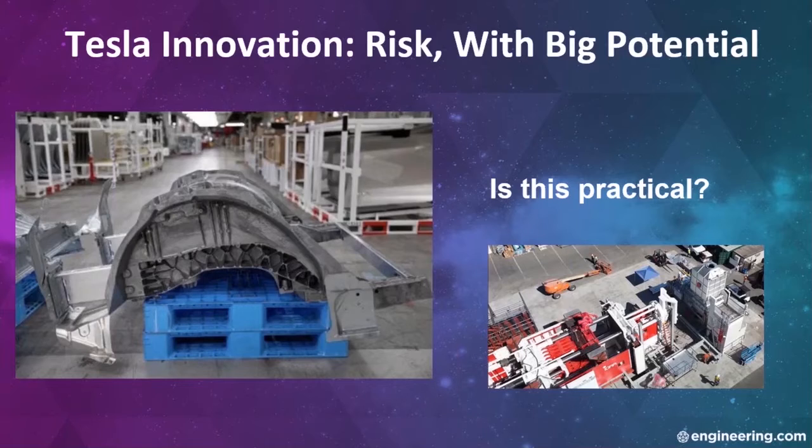Now, to attain the desired million unit per year production rate, multiple machines are going to be used, and Musk has stated that he expects a 30% reduction in factory floor space due to the savings from part consolidation, a 20% reduction in labor costs in vehicle assembly. Now, this is going to work. Structurally, doing this front and back of a stressed member battery pack means passing the loads in a way that will have to take those bending moments assumed by the torque boxes of regular auto unit construction.